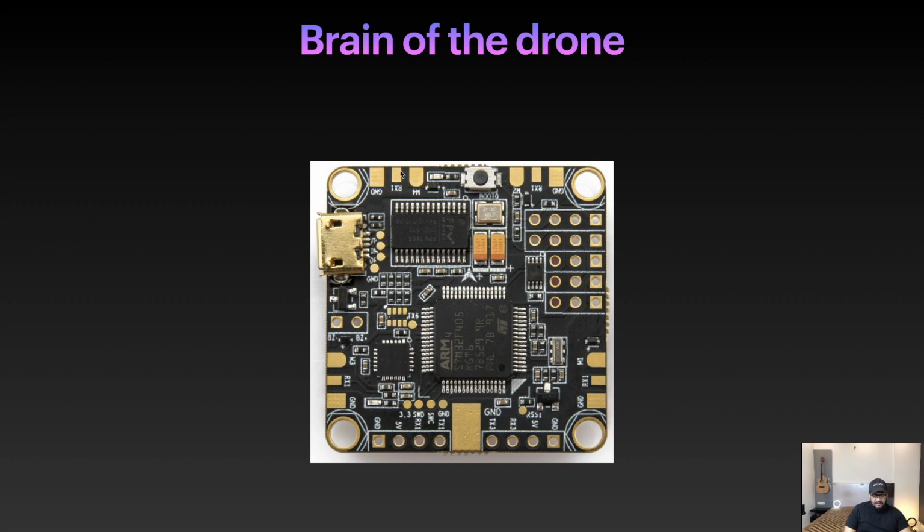You can see that over here, these are the pads where you solder the ESC wires, which your flight controller and ESC will communicate through. So these are the solder pads where you can solder the signal wire of your ESC. And over here you can see ground, 5 volt, RX and TX. These are the UARTs, and here you can solder the receiver. If your receiver works on S.Bus, it uses a UART for the communication. UART is a serial communication protocol, universal asynchronous receiver transmitter, and over here you plug the receiver.